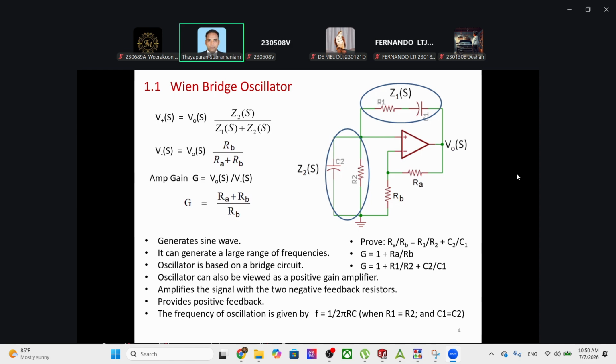because we have some faulty components in the basket, and you have to measure the op-amp performance. How do you measure it? Simply use RA, RB and the op-amp alone. Then it becomes a non-inverting amplifier. Just give one sinusoidal waveform to the plus terminal, measure the output and see whether the amplifier functionality is correct with the RA-RB magnification factor. Then your amplifier is ready.